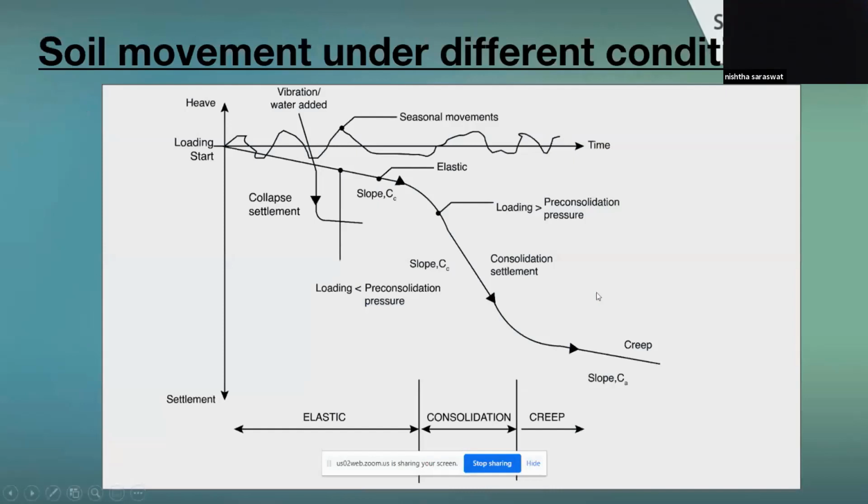I also want to share a bit in detail about consolidation in clay soil. So for example, in case of clay soil, there is pore water pressure when we apply loads. To begin with, for example, there is a soil with only air particles. We apply a load, delta sigma z, then the soil particles will compress, and the load will be taken by the soil skeleton. If I am applying an effective load, it will be taken by the soil skeleton. So my total load will be sigma z plus delta sigma z when there is only air.